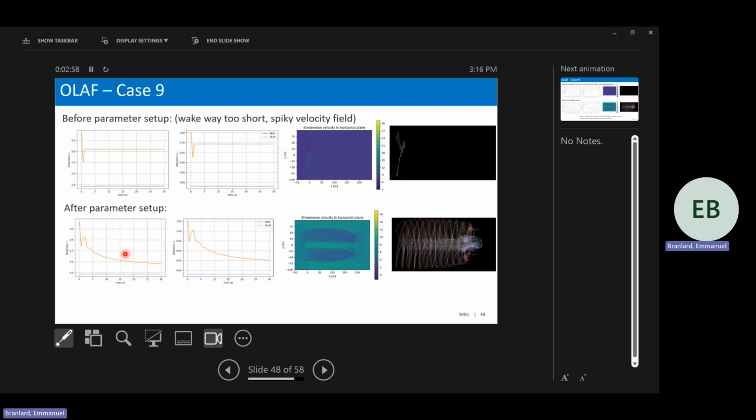So you have an example in the package. You could try to run it, and the first time you run it, you'll also have a Python script that does some plots for you, and you'll notice the results are crazy. I didn't zoom in, but the power coefficient is 0.8, the thrust coefficient is 1.0. So if you run OLAF and you have crazy values, something is wrong, and most likely you need to retune the parameters by running this Python script.